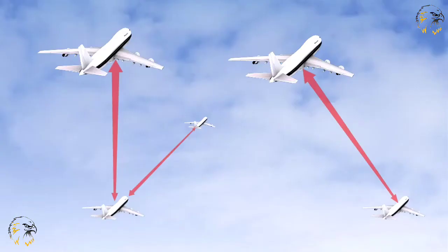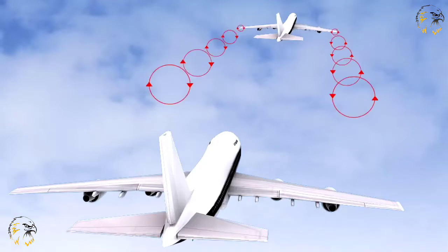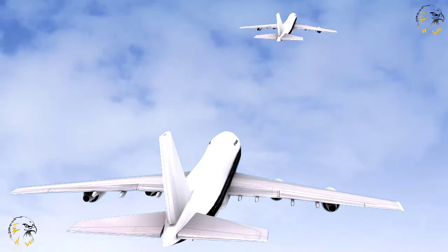Within controlled airspace, the ATS service will make sure that all controlled flights are separated from each other to comply with the first requirement of the service, that is, to prevent collision. Separation can be achieved by vertical separation, horizontal separation, or a mixture of both, composite separation. Such separation is applied as a defined standard and is known as separation minima. Separation can also be introduced to achieve spacing between aircraft that may be affected by wake turbulence, and to facilitate timed arrivals and departures at aerodromes.